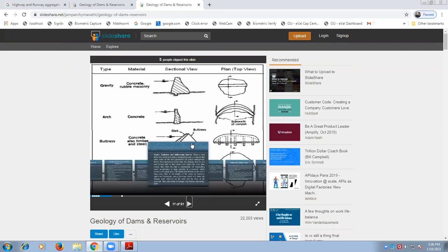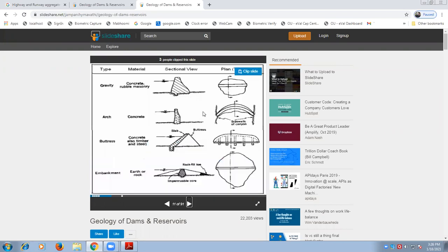Now there is the gravity dam. We have a short description, as you can see in this figure. Gravity dams, first of all, you need to know that they are wall-like concrete structures which are very heavy and massive. The entire weight acts vertically downwards. The total force is transferred on a small area of the foundation, and wherever you have stable rocks, you can construct a gravity dam.